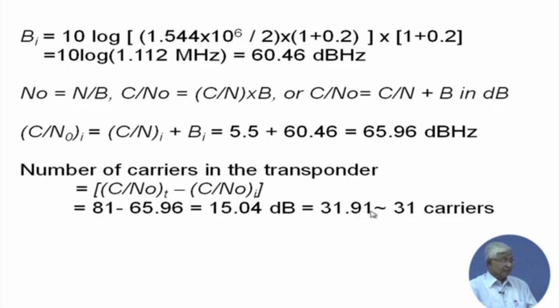So, you will have some extra bandwidth available, that is the advantage. Again, if you do the calculation, your efficiency will be different, and maybe that extra carrier space you get, 0.91, can be distributed in terms of guard band or in terms of slightly loose filters, whichever way. But here 31 carriers is the maximum possible in this particular case.